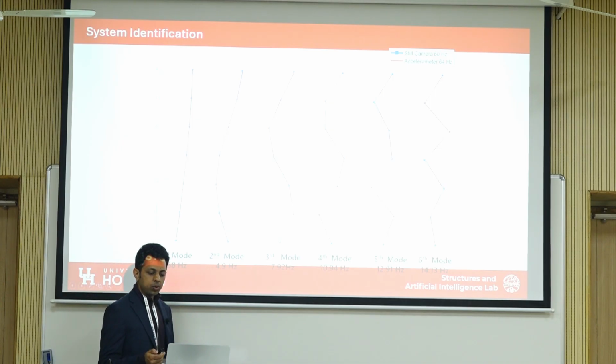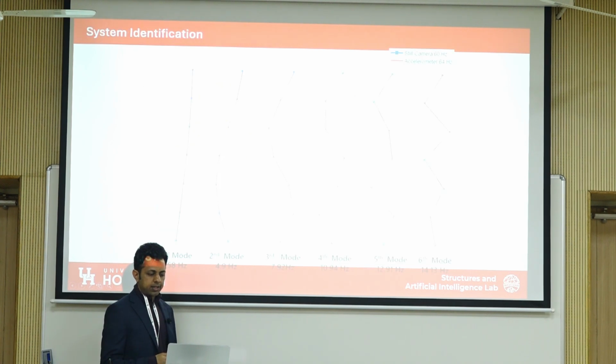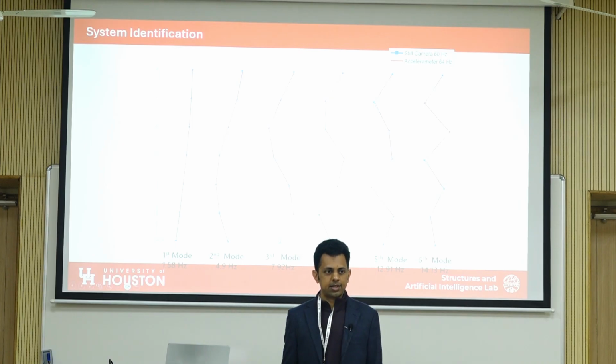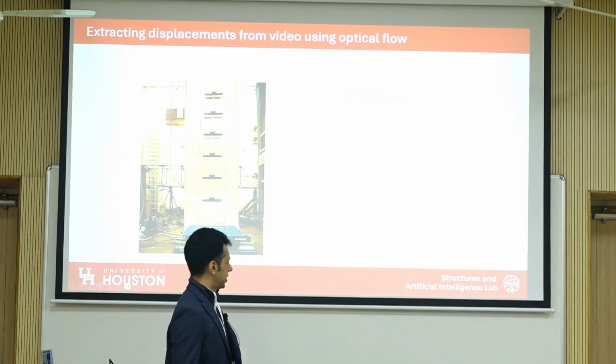But another thing you can do with videos, of course this is a video here, is you can directly band pass these videos. Yes, it's a combination of all these mode shapes. So you're identifying each mode shape from the displacement.